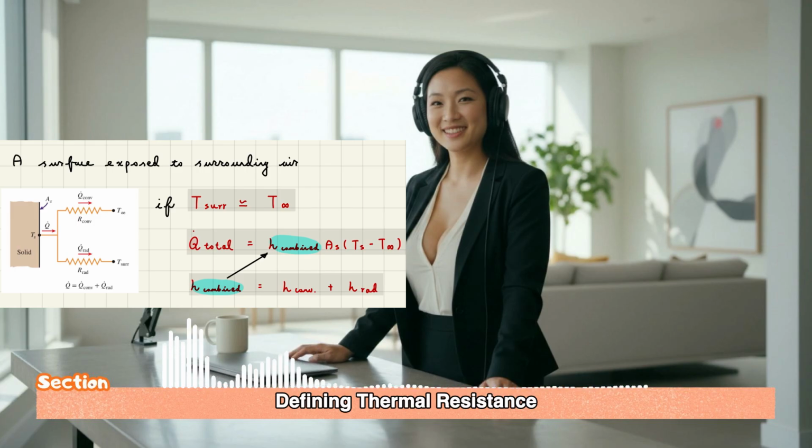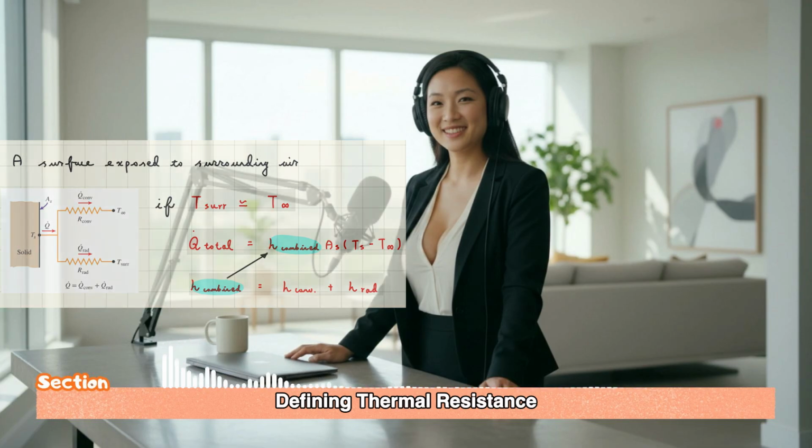And since they are parallel resistances, we could use the reciprocal rule to combine them. But for practical applications, especially when the surrounding temperature is close to the air temperature, we simplify. We just use a combined heat transfer coefficient. Exactly. h_combined equals h_conv plus h_rad. And that's a huge convenience for engineers, right? It is. It lets us collapse those two parallel paths into a single equivalent resistance. And that keeps the rest of our analysis purely in series, which is just mathematically so much easier.